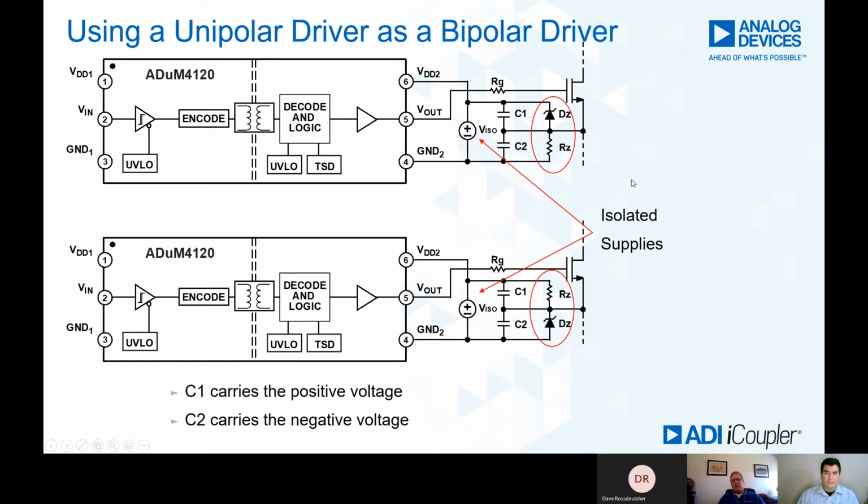Okay. Now, is there any particular benefit in that series Zener regulator circuit, whether the Zener diode is in the top position or the lower position? So putting it in the top will have your positive rail more closely regulated. And if you put it in the bottom, you'll have a more closely regulated negative drive. Most people want the positive drive to be more accurate.